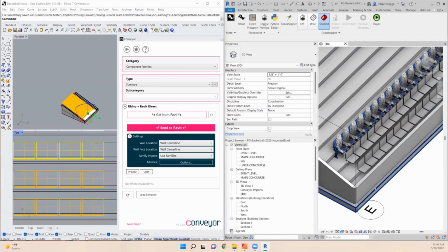Because I could envision that if you're in a concept or schematic design phase that has a requirement to have maybe some seats represented in the Revit model, then maybe you just use the direct shape method because it's just fast and there's lower overhead. You click the object and you send it over and it will generate the in place representation.